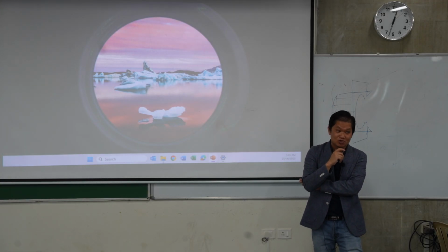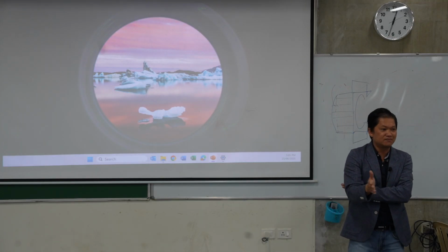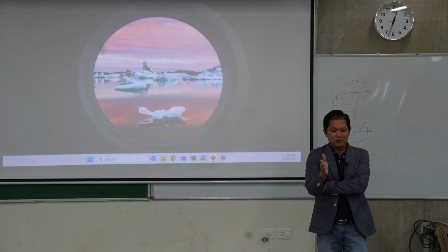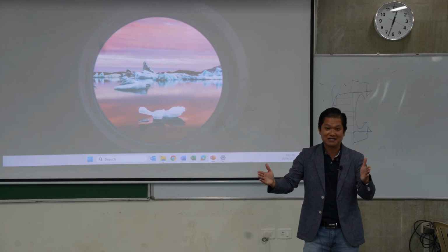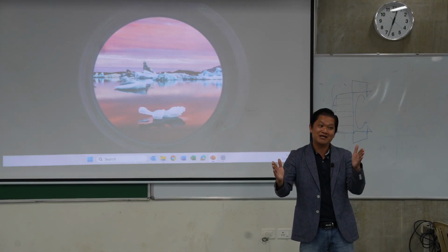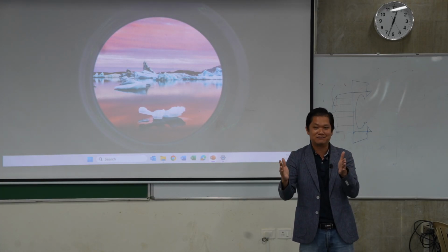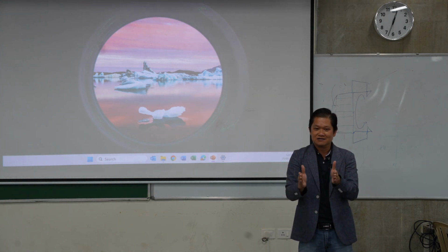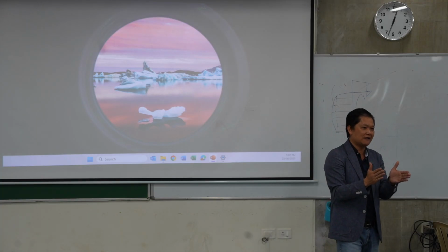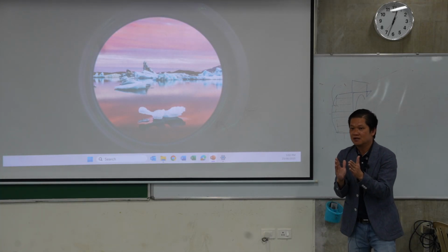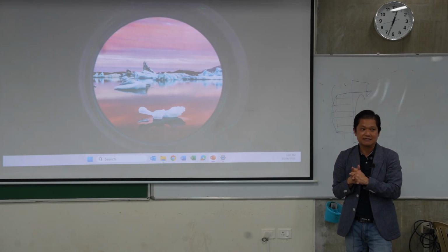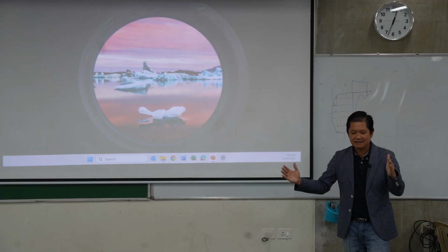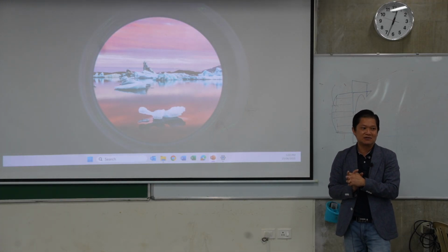We haven't got to distortional buckling and shear, because as I mentioned before, with distortional buckling you need a longer half-wavelength, right? You get about 6 times the depth or something, and when you get something more than 3 times the depth, then the bending will come in straight away. Then the interaction is meaningless. So I think it just works for local buckling when you consider a very short span, and the interaction maybe up to 2.5 at the moment. When we test in the lab, we can see the interaction with shear. But other than that, up to 3, then bending just comes in straight away.